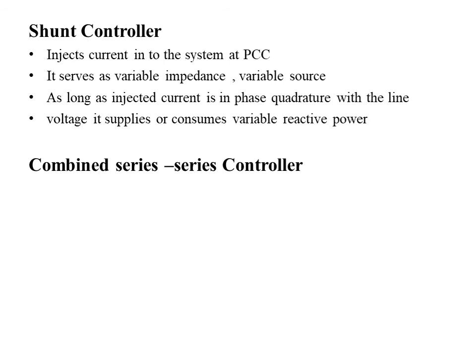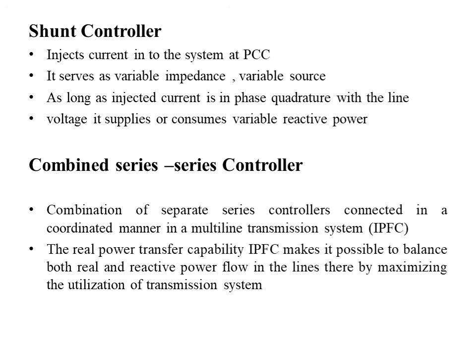The next type of controller is the combined series controller. A combination of separate series controllers can be connected in a coordinated manner in a multi-line transmission system. One example is IPFC. IPFC makes it possible to balance both real and reactive power flow in the lines, thereby maximizing utilization of the transmission system.